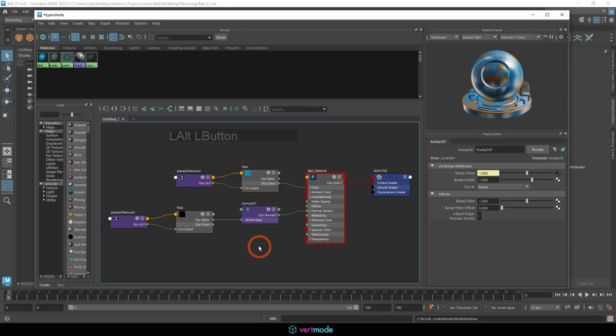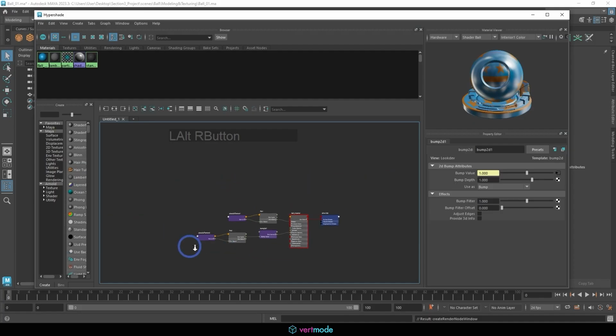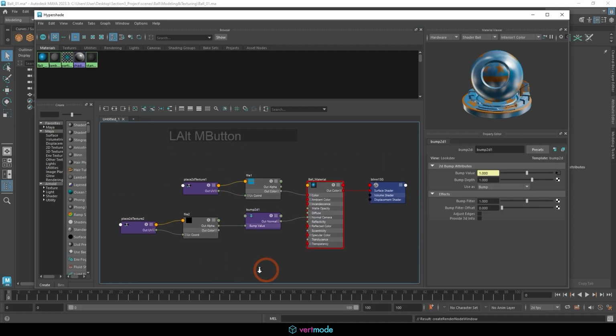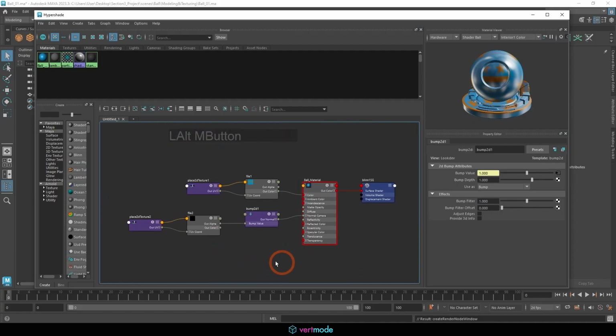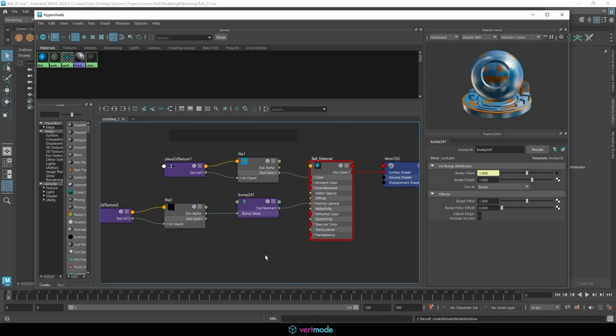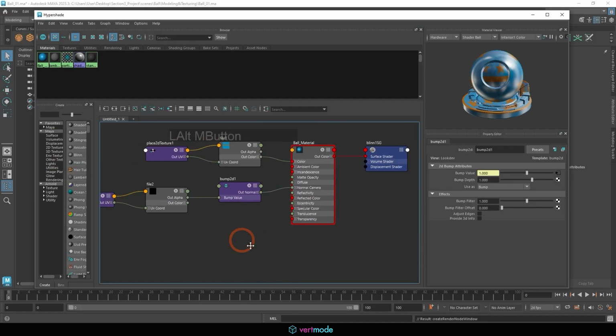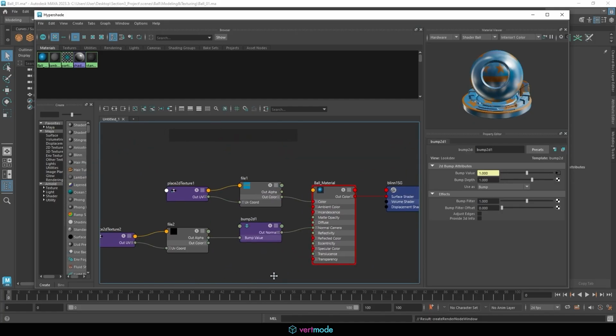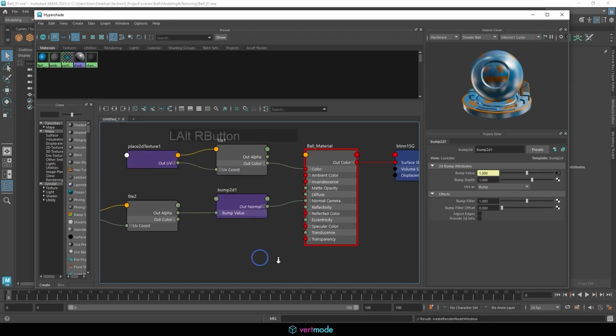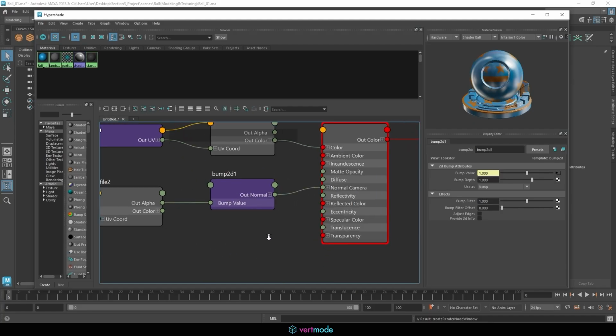The only thing that doesn't really do anything is going to be Alt and left click, surprisingly. And that's because this is 2D space now. It's not 3D space. And this is going to be common throughout Maya. Whenever you're navigating a 2D menu, that Alt plus middle mouse button is going to be side to side, just like it is in 3D space. And the Alt right click is going to zoom.